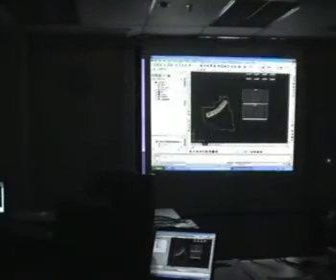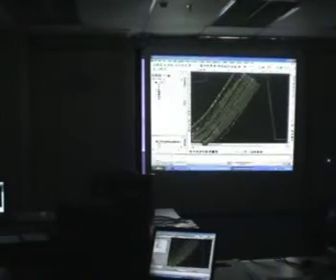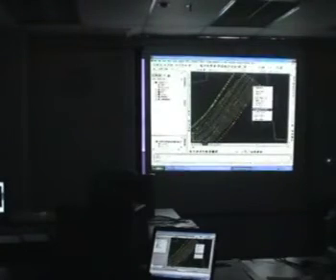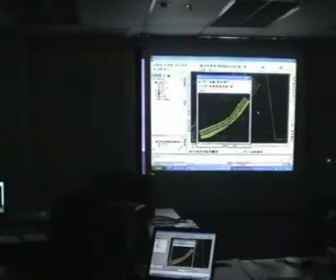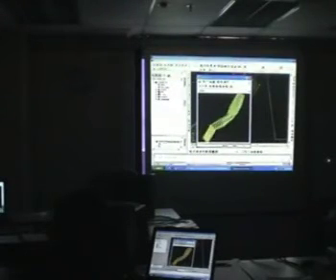drawing. So let's begin now. This is the corridor that has been created for this project. And I'm just going to select the corridor, look at the object viewer. Hope it works. The object viewer basically is for you to view the object. They've got all these zooms and the shape and the orbit. This is an advantage in the sense that with AutoCAD you also have all the orbits, but you orbit and you view everything in the drawing. With the object viewer, you can just select one object. I want to see what this looks like. So it's a lot easier to check what has been done.